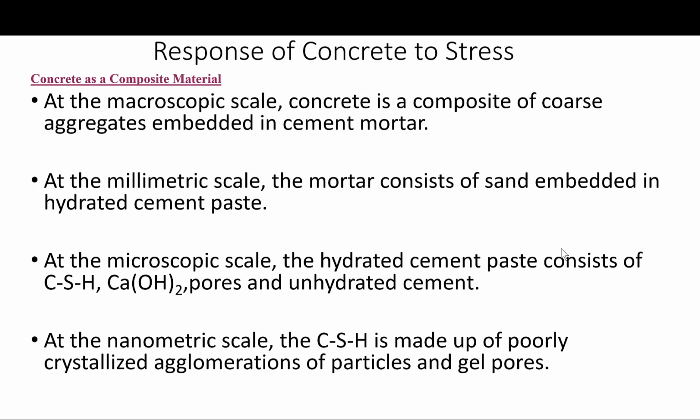Okay, so on a still finer submicroscopic scale, the calcium silicate hydrate is a mixture of poorly crystalline particles of a variety of shapes and chemical compositions, and a more or less continuous system of gel pores, which also may be dry or partially or completely filled with water, as we explained before.